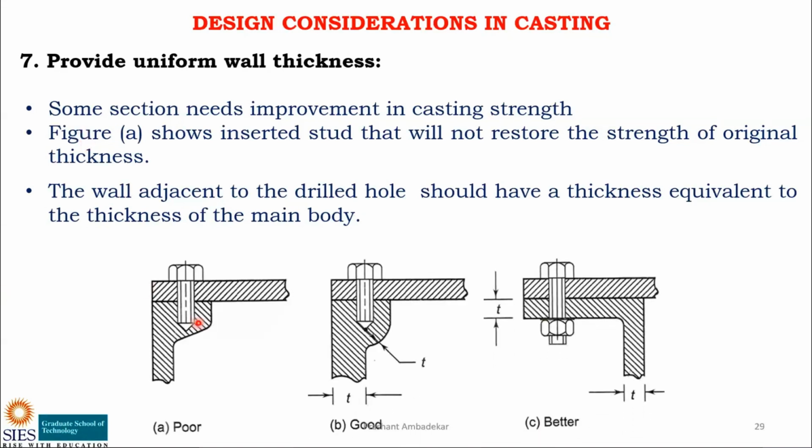You can see here. This is the first case. So this is part number 1 and this horizontal is part number 2. These two are to be joined. Now these are two separate parts and they have to be separate parts based on maybe the design or something like that. Then what are the ways available with you? Either drill a hole in this and use a screw. Second way is you can use welding over here, or you can use riveting over here, something like this.